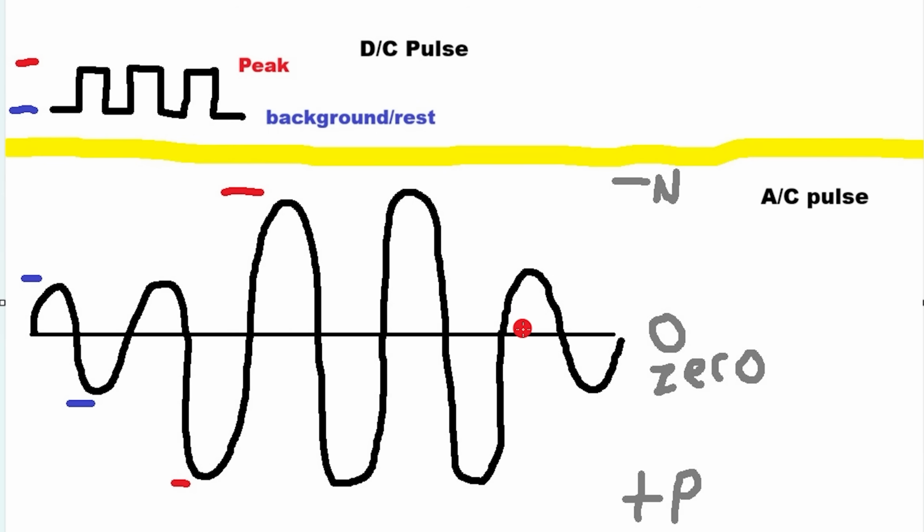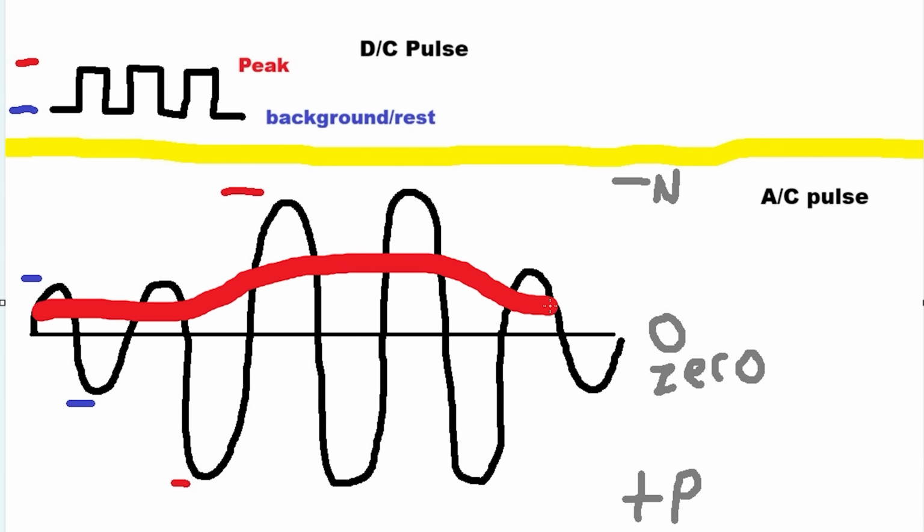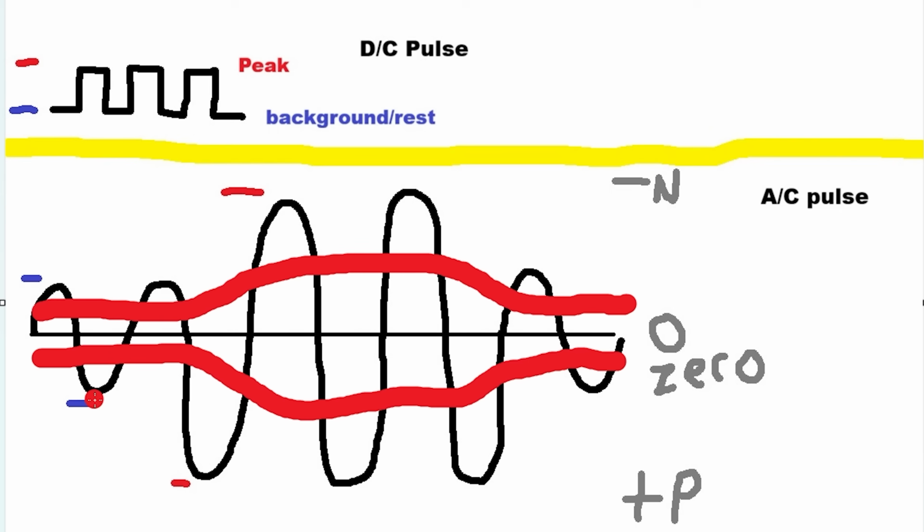I know that sounds confusing, but what you really need to look at this as is like an average heat input. So your heat input on this side would actually look something like this. Because yes, it has peaks and valleys, but the overall average heat input is going up and down. Same thing over here. Now keep in mind that the heat input of the rising and falling current with the AC wave is playing a role, as is the actual pulse. So like this area right here where you're not pulsing, that's the average, and then the pulse brings the average up here, so more heat input.